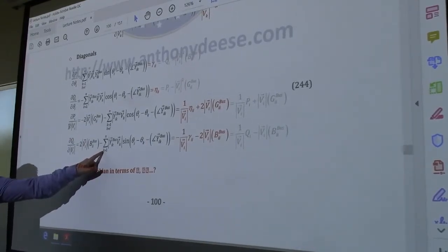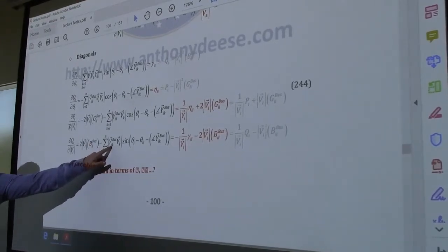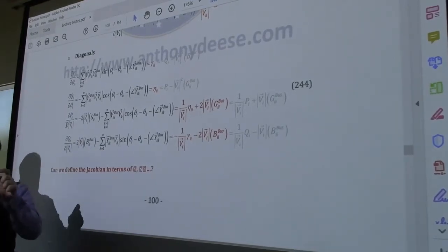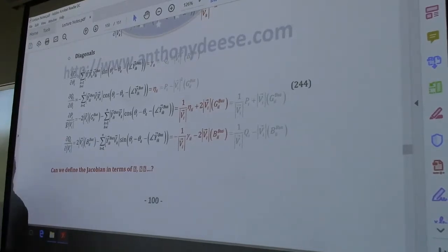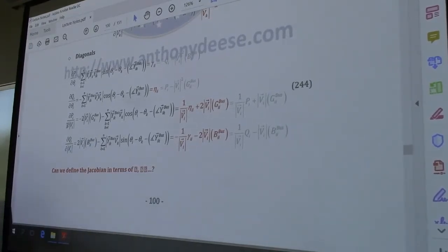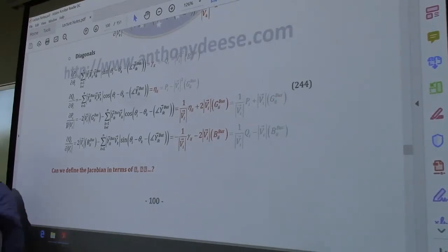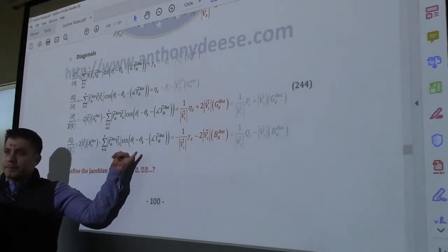And so k to n, you're going to be summing for all the different combinations where a line exists, right? Y bus ik will be 0 if there's no line between buses i and k. So like, let's say there's 5 buses, right? So you could have as many as 5 terms here in this sum.